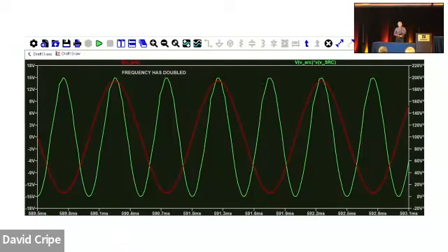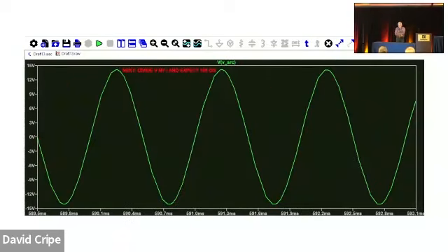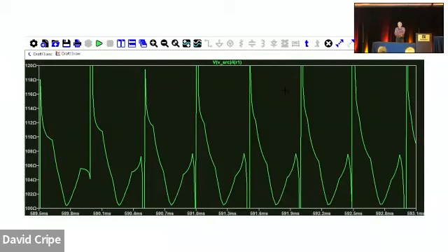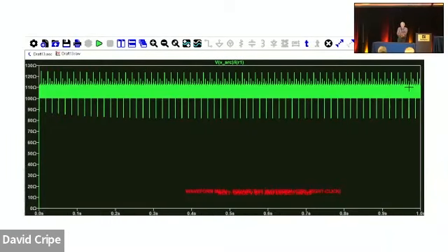But something a little more complex maybe will be to take that waveform, it's basically just the source voltage, and divide it by the current coming out of it. That's the current to that resistor that it's connected to. And I'm thinking, well, it's going to give me something like ohms. Well, it's a pretty ugly plot. If we zoom out a little bit, okay, there it is. It's real spiky. It seems to be centered somewhere around 105 ohms.